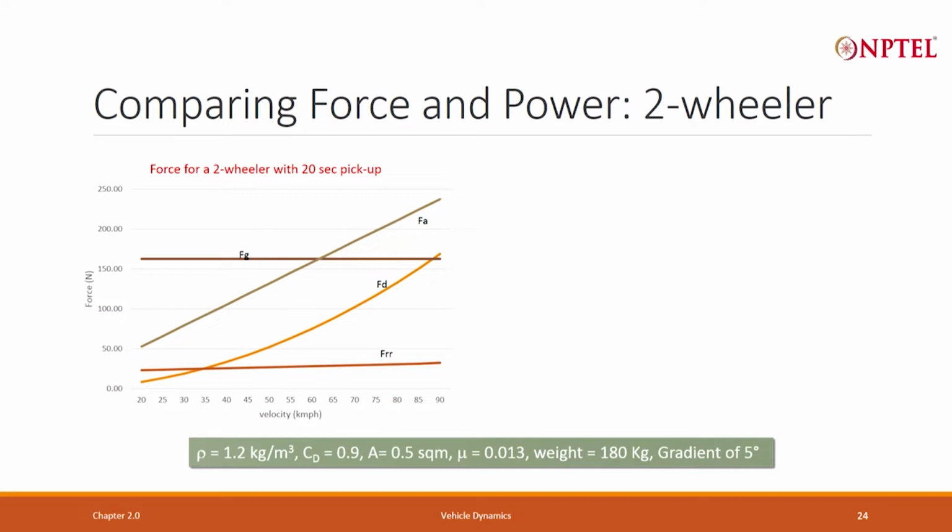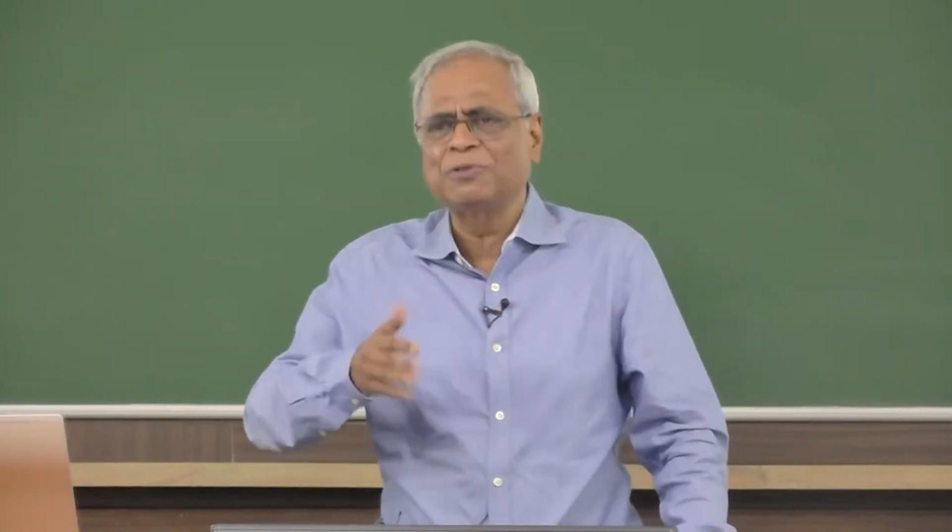At 60 kilometer, this may be 60 to 70 Newtons. But as it goes to higher velocity like 80 kilometers or 90 kilometers, the force required due to drag increases significantly. And we will see the implication of that. When we go forward, we will see that the drag force will dominate at higher velocity. At low velocity, not too much.